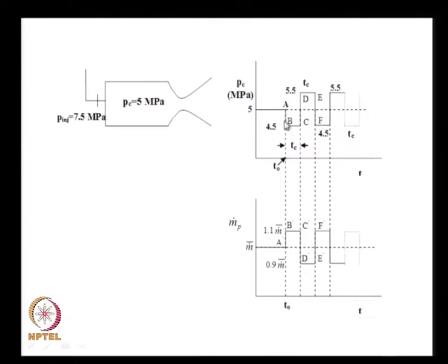then this sudden dip in pressure allows more fluid to come inside the chamber, and when more fluid comes inside the chamber it does not burn instantaneously, but it takes a small time. Tc is what we defined in the last class, namely it takes Tc time to burn, and when it burns, since more propellant comes inside the chamber, there is an increase in pressure. After this decrease there is a time delay and thereafter the pressure increases.